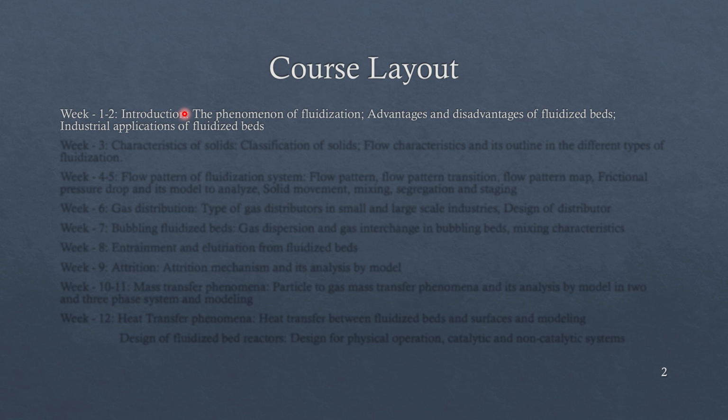The thing is, in fluidized beds, the chances of catalyst erosion, that is particle erosion, are very high. Also, in certain reactions, catalysts are very costly, as you all know. So, in those cases, it would not be efficient to prefer fluidized beds.